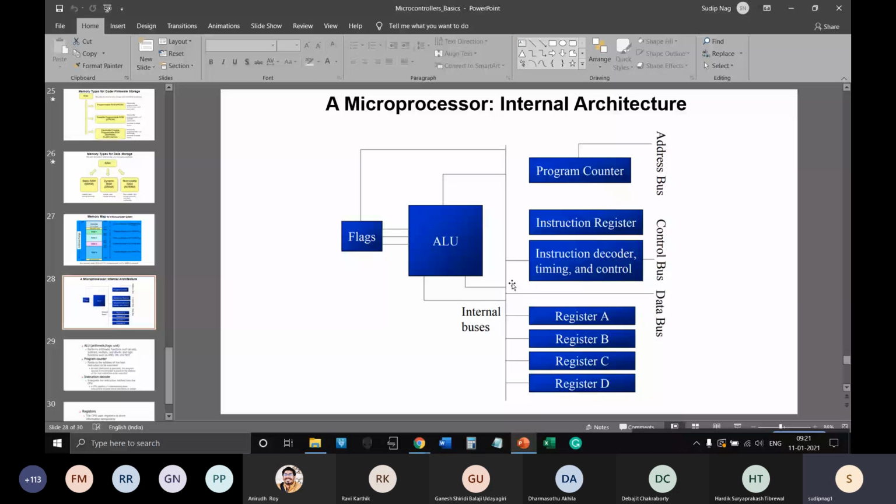We have technology to fabricate both memory and microprocessor side by side within the same silicon die. Memory means a certain number of transistors. The microprocessor is also a certain number of transistors with digital connections, obviously, most of the time. So they can fabricate side by side and make interconnections between them. So in modern microcontrollers, memory is within the same chip, but outside the boundary of the microprocessor.